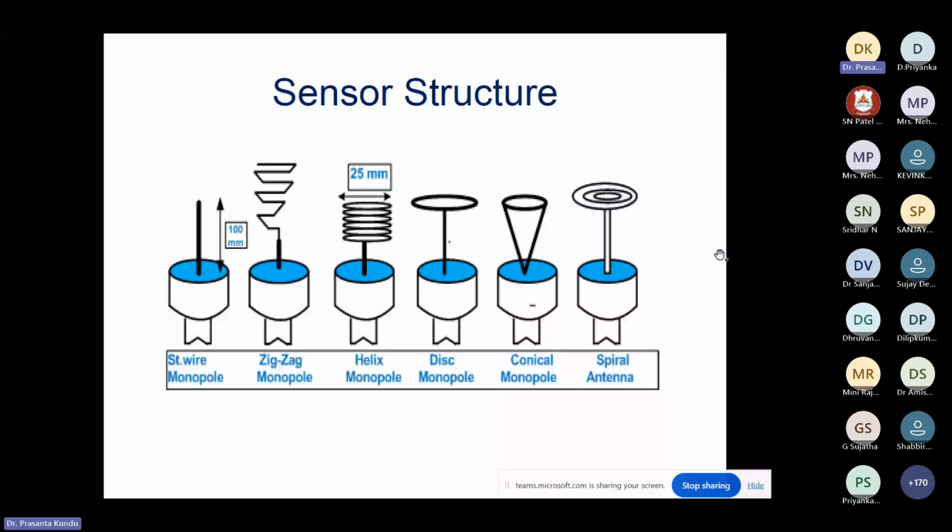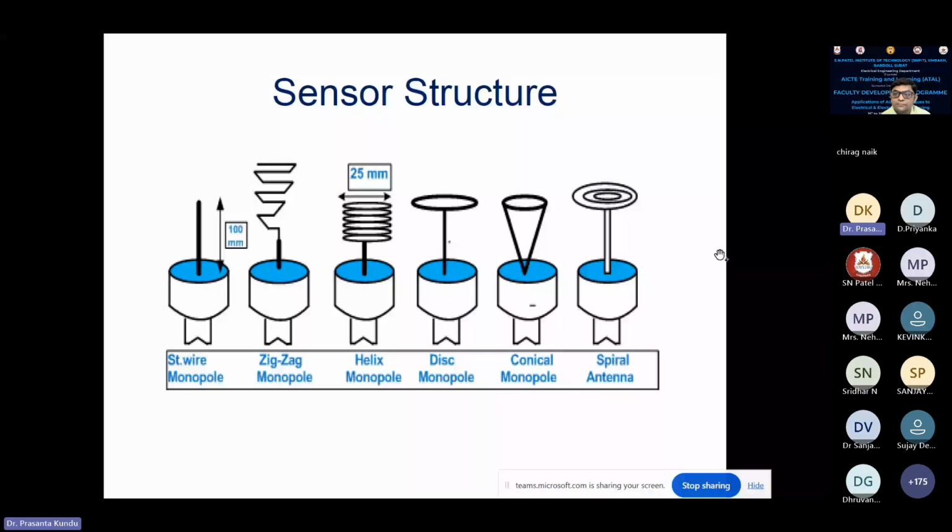In the lab, what we find out is the sensitivity. If the partial discharge is occurring at a very small magnitude and the UHF sensor is placed a little bit away from it, say for example 1 meter, it is very difficult if there is no sensitive measurement. So not all sensors may give the required sensitivity here.